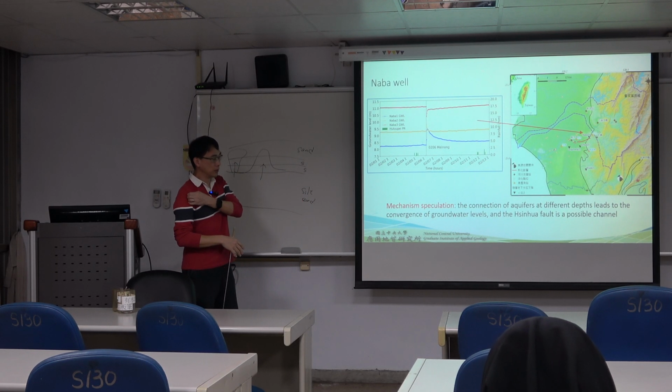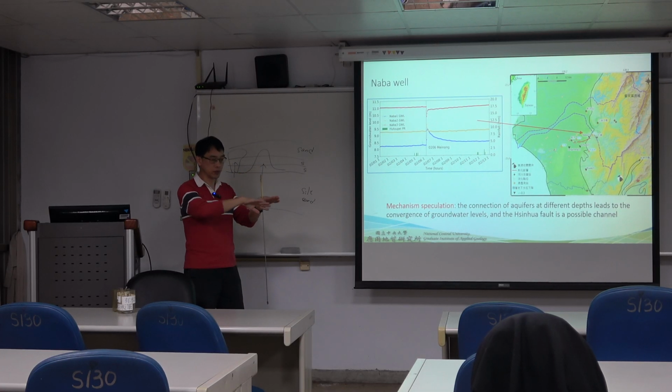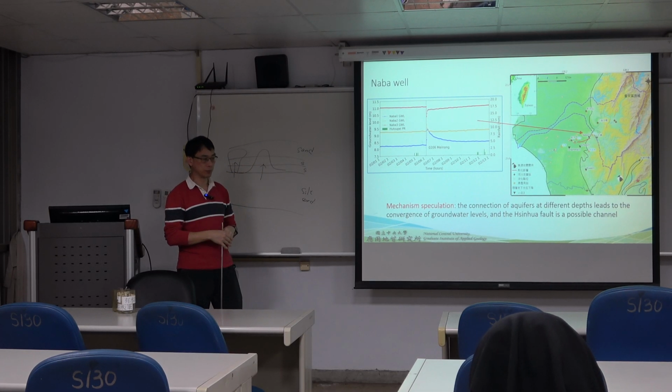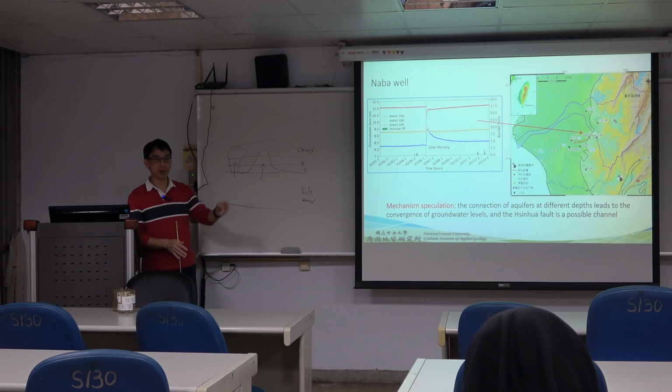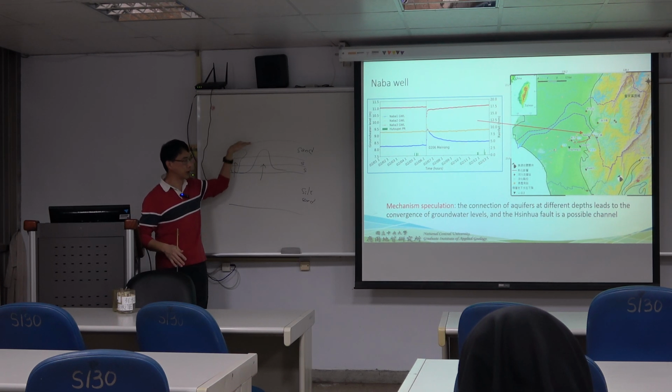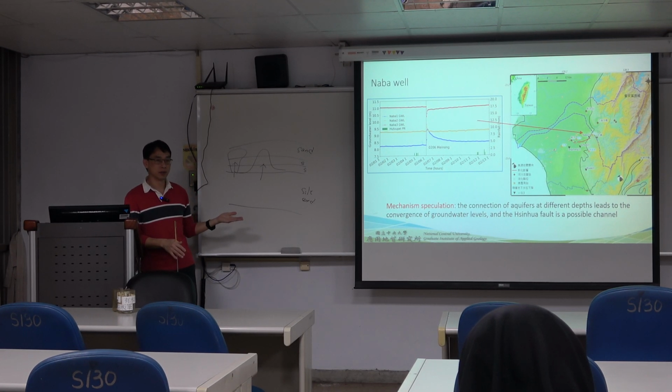Another issue is that some professors use building tilt or surface deformations to define liquefaction, but some geotechnicians will say, oh, this is not liquefaction, it's just deformation. If you see this kind of uplift, or the surface has uplift behavior, or you see buildings tilt, it might imply that liquefaction occurred below. So what that professor said, I agree with that.